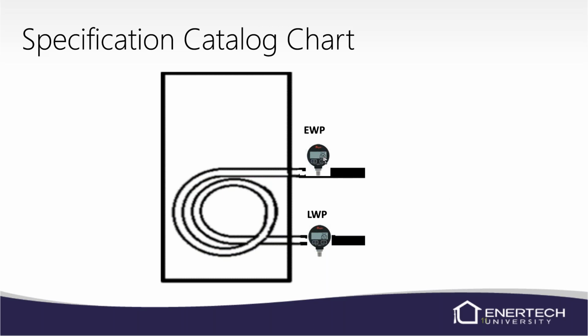But basically, we're going to check pressure in and then pressure out and do the math on that and get our pressure difference. The pressure in should always be higher than the pressure out. If it's not, then you've got your flow reversed.